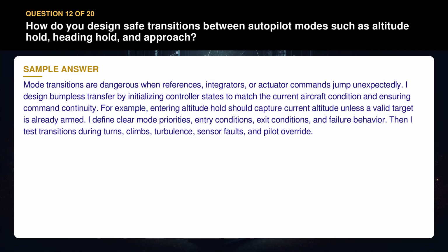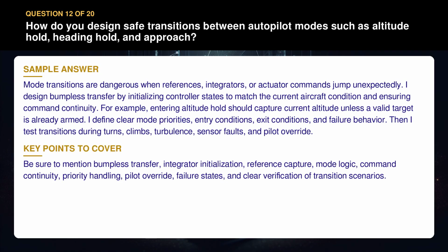I define clear mode priorities, entry conditions, exit conditions, and failure behavior. Then I test transitions during turns, climbs, turbulence, sensor faults, and pilot override. Be sure to mention bumpless transfer, integrator initialization, reference capture, mode logic, command continuity, priority handling, pilot override, failure states, and clear verification of transition scenarios.